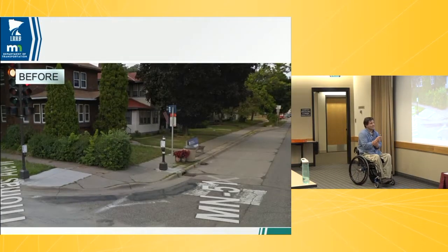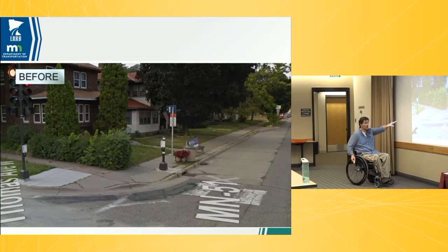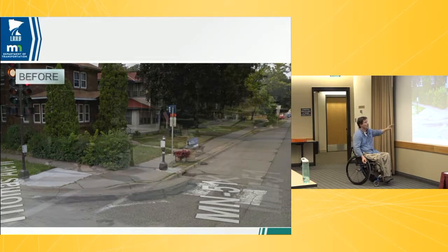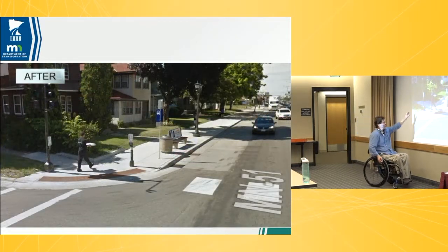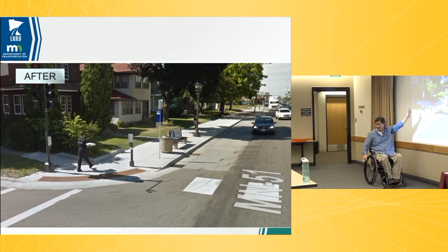Here is a signalized intersection, with narrow sidewalks for street furniture. There was existing APS on this, obviously no curb ramp upgrades. The APS doesn't meet standards either, but we're going to see what we can do here. There's a push button on the pedestal. We're going to move it over here. The city didn't want extra clutter. $5,000, move a pedestal, kind of move on.